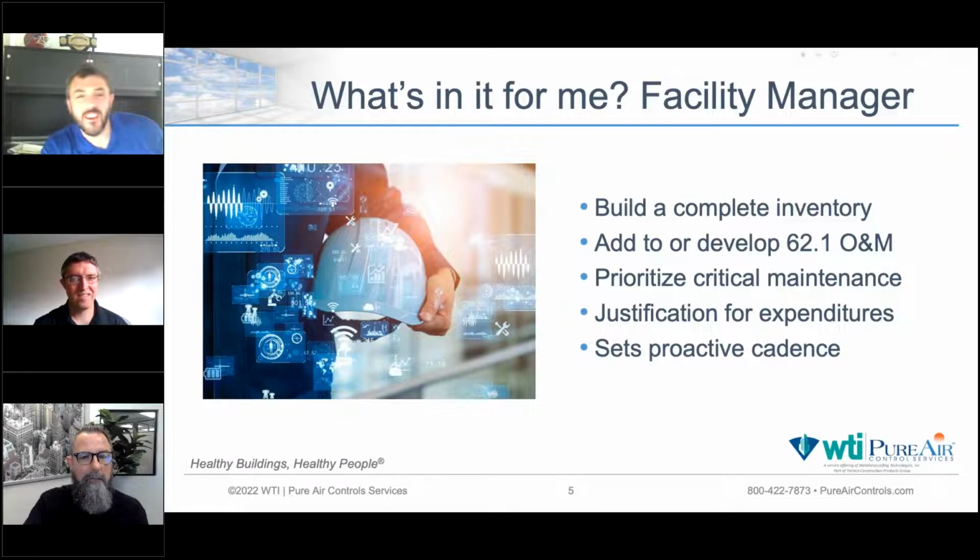And he found out that for this particular unit, which had a return fan and a supply fan, the entry of the discharge in the return section, that damper was closed off, and the outside air damper was closed off. So the unit was just starving for air, creating all that pressure that forced him to really struggle to get the air handler open.